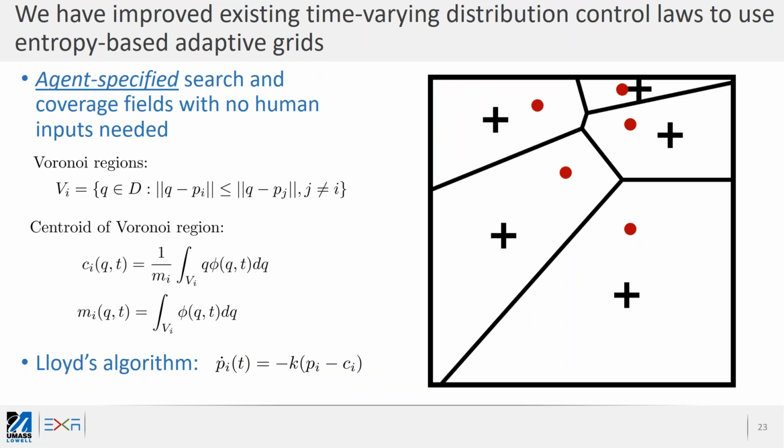So now let's just talk about a basic algorithm over here that kind of is used to explore the world. So the red dots on the right are the robots, and we use Voronoi regions, which are essentially perpendicular. If you look at the line joining the robots, you'll notice that the boundaries are essentially perpendicular bisectors of those lines joining the robots. So the Voronoi diagrams essentially create these regions in that specific fashion. So what we are looking for now is to have a uniform distribution across this entire square world.